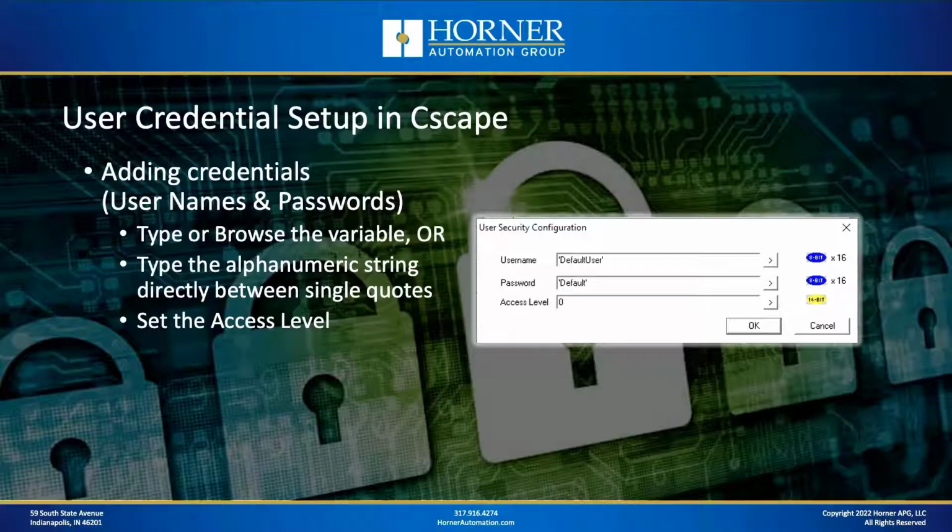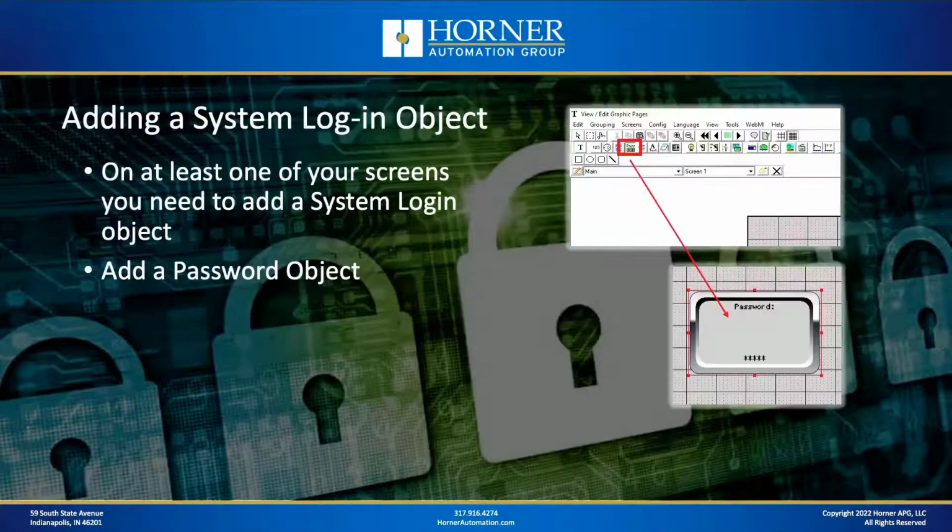That's the approach I usually take. And then of course with each set of credentials, you set the access level that that particular set of credentials has. So we've done two things so far. The first thing we did was on key graphic objects that had an action, we elevated the access level. The next thing we did was we went ahead and added in a number of sets of user credentials, as many as 255. The last step we need to do is we need to give the operator some way of